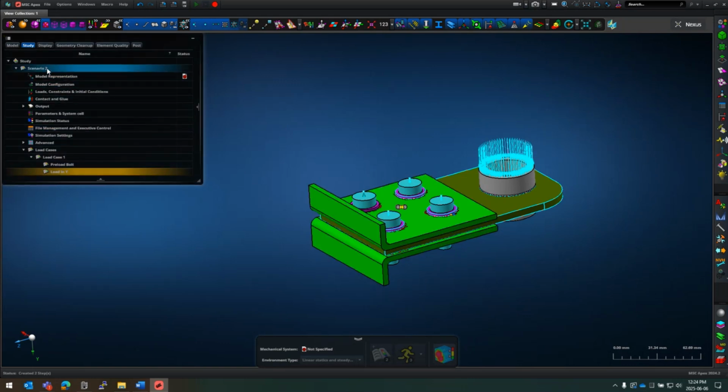Okay, now let's start from the top and just give it a better name. Scenario T sounds so last century. Okay, so let's call this bolt preload with side load. I mean, I can give better names than that. But notice this is the first time I've added underscores. You don't need it. It just makes it easier, because this will be the name of the Nastran file that we're going to run, and command windows and so on really don't like spaces.